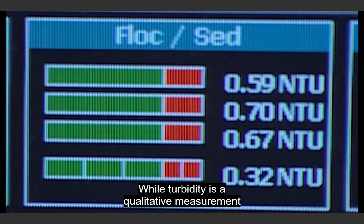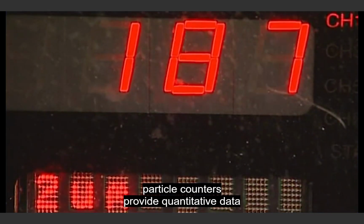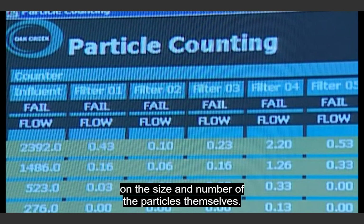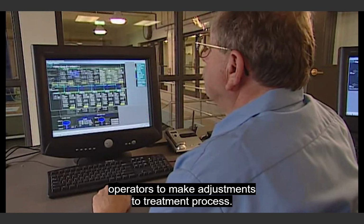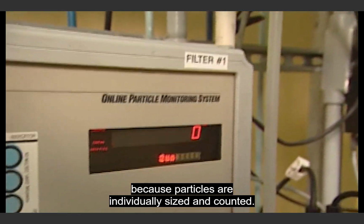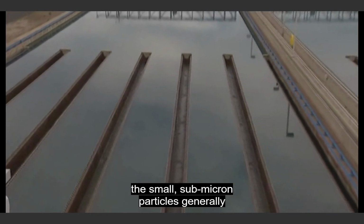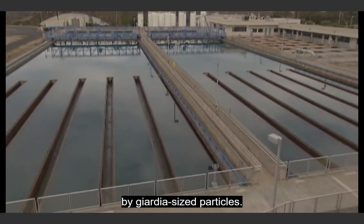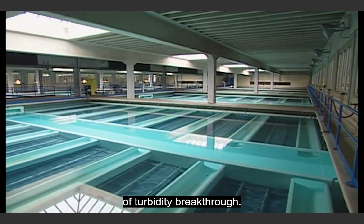While turbidity is a qualitative measurement of the amount of particulate matter in water, particle counters provide quantitative data on the size and number of the particles themselves. The additional information allows operators to make adjustments to the treatment process. Particle counters provide more information than turbidimeters because particles are individually sized and counted. In a conventional filtration plant, the small submicron particles generally break through first, followed later by Giardia-sized particles. Therefore, particle breakthrough is often a good predictor of turbidity breakthrough.